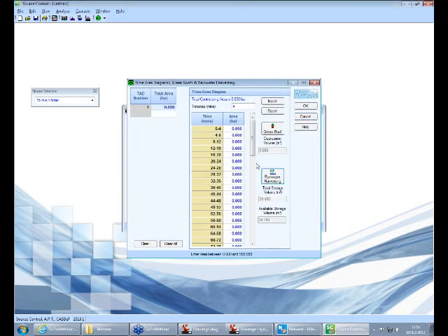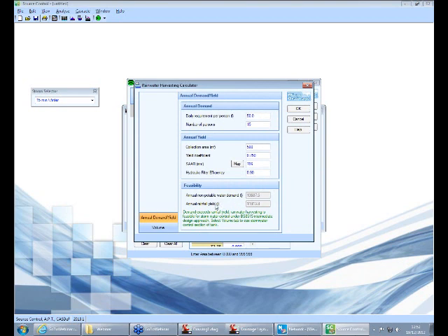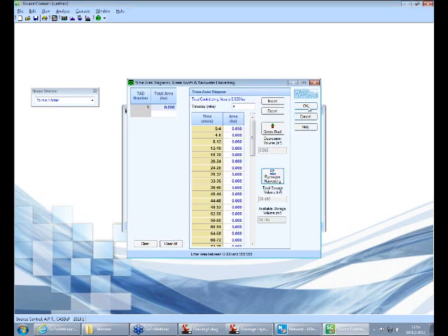If you find that your demand isn't as great as your supply, the standards recommend that you run continuous analysis and do a more complicated sort of analysis to work out whether you could store some stormwater in your rainwater harvesting tanks. But in this scenario, where it goes green, we know we're good to use it.